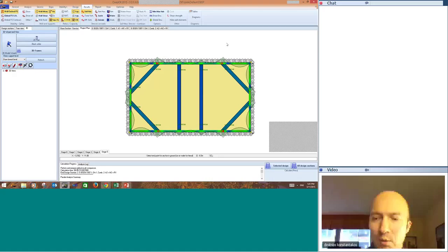The way it works is that it picks up the loads from the 2D analysis, and it assumes the worst load scenario that you have used in each design section or each wall section. You can even further, if you want, specify concentrated loads specifically, where you might have a building and simulate that you have a higher load there. So let's wait and see the numbers that we get.